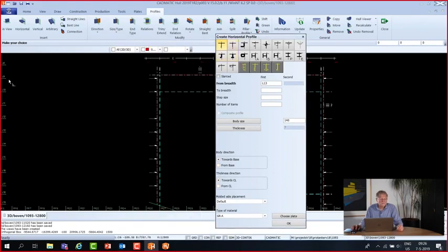That has quite an advantage, especially in the basic design, because when there's a change in frame spacing, you only need to edit the file behind this, and then all the structure will be relocated according to the new position of the grid.